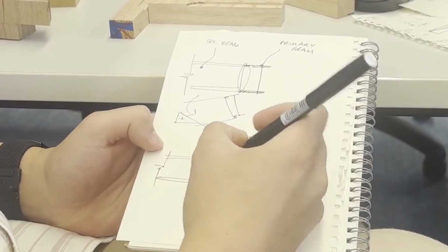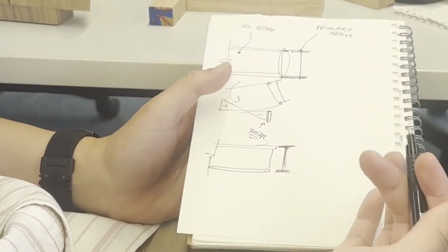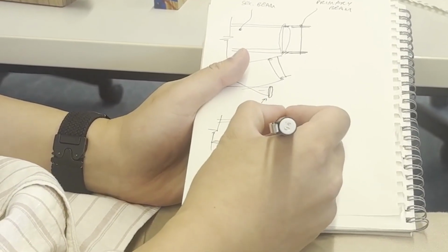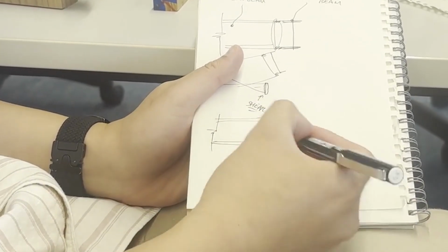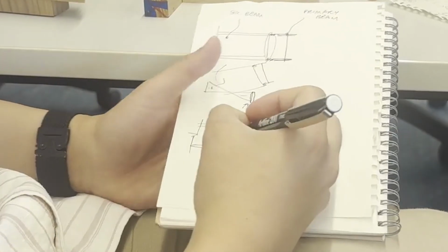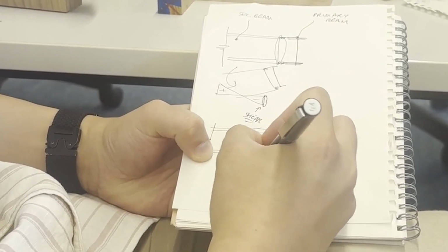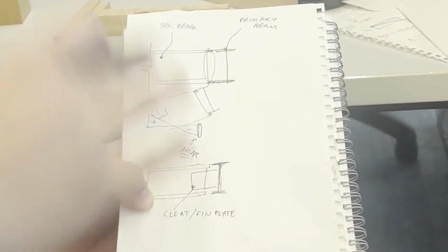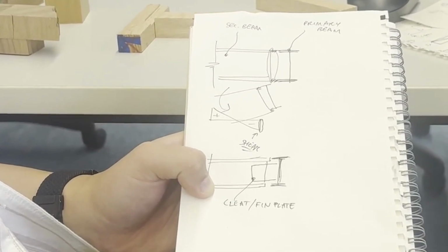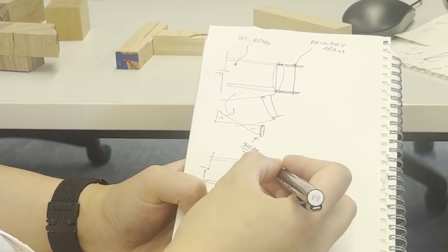But basically, if I were to do that again, there are two ways to do it. I'll tell you the less optimal way first. The less optimal way is you do a cleat, like you were mentioning before. A cleat is a type of plate. This is a cleat. It's called a fin plate in some parts of the world, but in Australia we call it a cleat. It makes more sense as a fin plate, because a fish has a fin, and it's just something sticking out, okay?